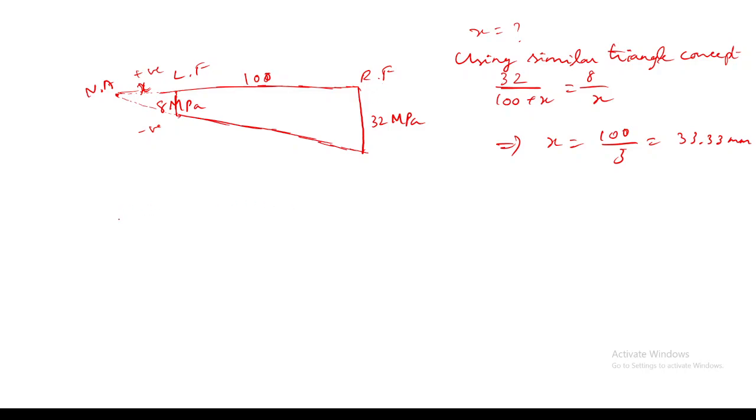For example, in a given beam, you can have the bending moment diagram like this. These two are parabolas. Here also the bending moment value is actually 0, but can you say this is the point of contraflexion? No, because the point of contraflexion is defined as where the bending moment actually changes sign. So we can't say the neutral axis is the point of contraflexion. Okay? Thank you, sir.